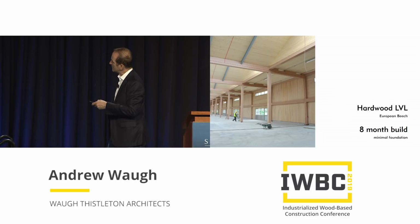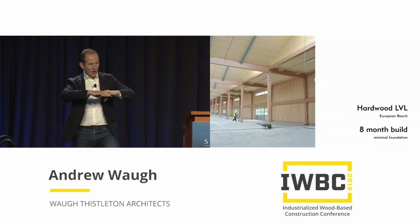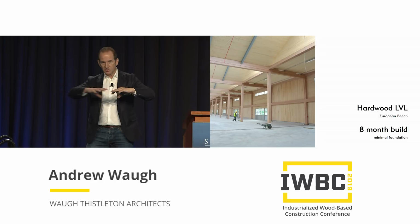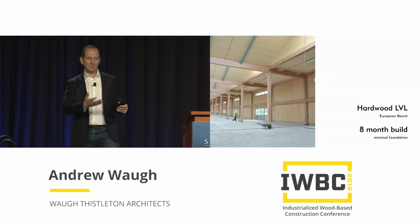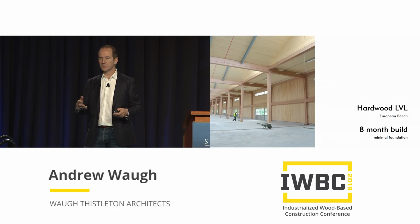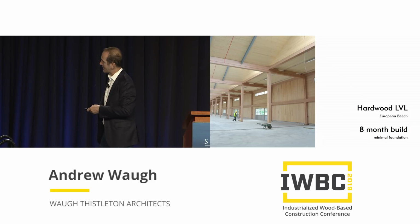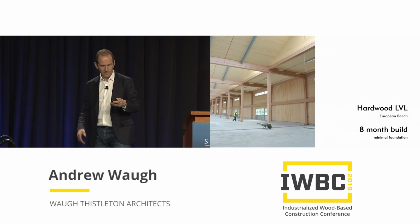So you can see here how beautiful these are, and the tolerances, how exact and precise they are. These little notches here are left open for servicing in the future. And because the building's so light, there's no really traditional foundation. In fact, the whole slab is just a stabilized earth slab. We just plowed some cement into the soil for about 1.5 meters down, and then put a screed on top. And there's just a little pad foundation under each column. Very simple, very straightforward construction.